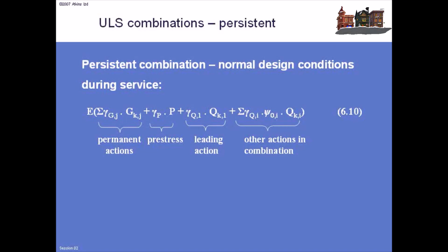There's a slide coming up, but the Eurocode basically gives you some exceptions. So clearly it would be a complete pain to have to consider everything else that you haven't considered. So there are general get-outs, like you never consider wind and temperature together. And that's really the same as we did before. And you generally don't need to consider snow at the same time as traffic loading, because you can't drive in a lot of snow, fairly obviously. So although this looks like you've got to consider everything together, what you do need to consider together is relatively small because of the exceptions.